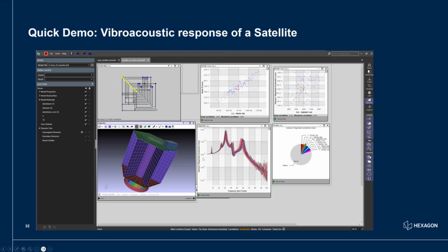You can see here, for example, a vibroacoustic case, and we can track, in terms of envelope, all the frequency response of a particular accelerometer, for example, or pressure, sound pressure, as it varies in frequency. So then we can go to a particular frequency range, let's say between 50 and 60 hertz, where it is starting to be audible, and we might decide, if this was a comfort issue, like in space there is no such need, but let's say we might decide to dwell down into that particular range and try to understand how we can reduce this peak, right?